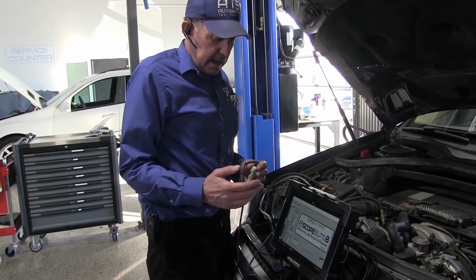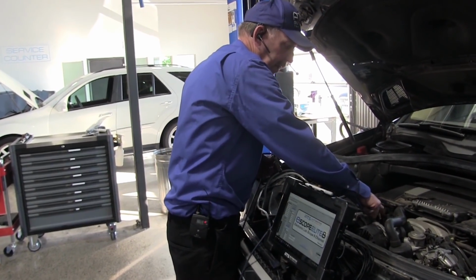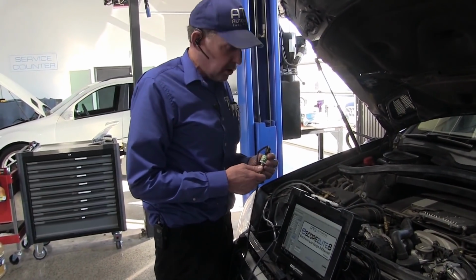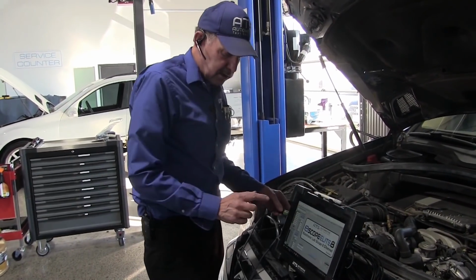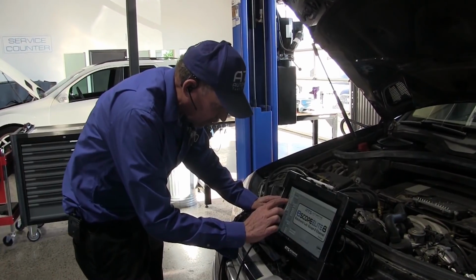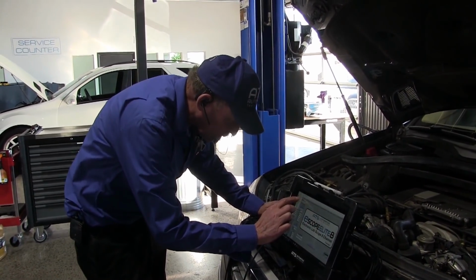Okay guys, I got my pressure fitting right here, and it does have a pressure fitting on the rail just like I thought, so I'm really lucky. I'm going to use a pressure transducer on this, so I brought this up. Now before I put the pressure transducer in, we want to set that up. So I've got it plugged into the scope on channel 1. We're going to go to a 300 pressure transducer.